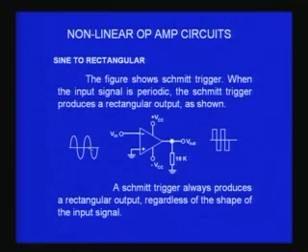It can be a sine wave, or a triangular wave or any other wave, as long as the excursions go towards both positive and negative voltages, and the amplitude is larger than a minimum of a few microvolts, 140 to 150 microvolts. You would find the output will always be a square wave between Vsat and minus Vsat, but the width or the period of this square wave will depend upon the threshold that you have provided for the other input.